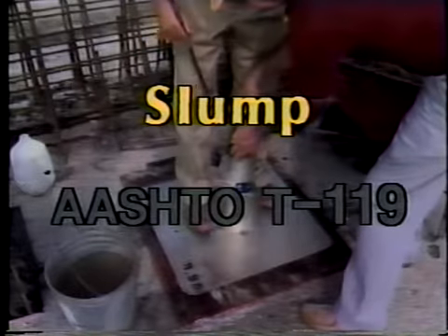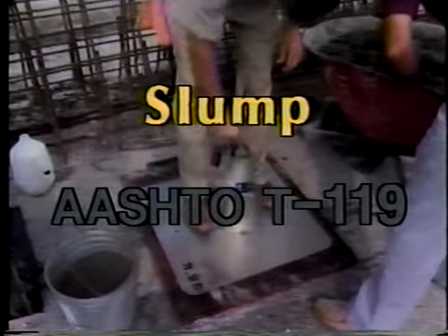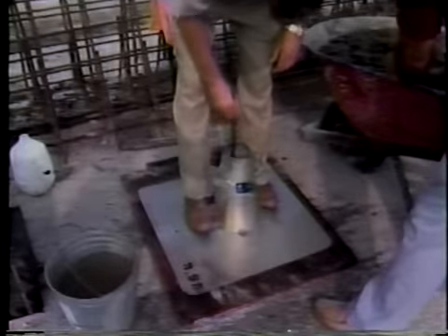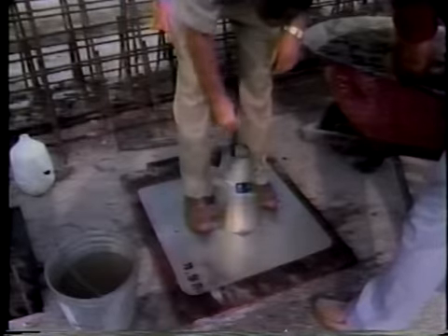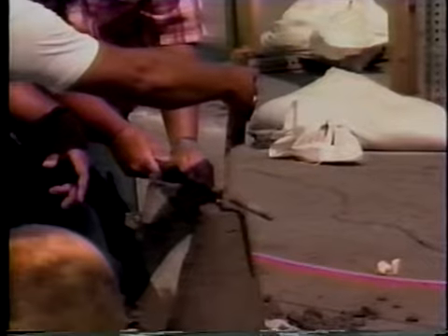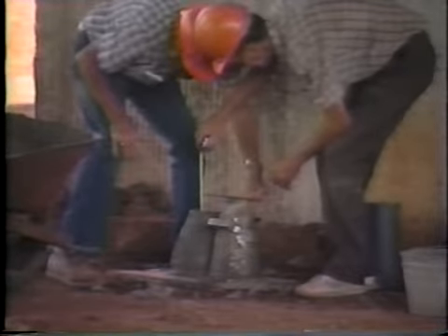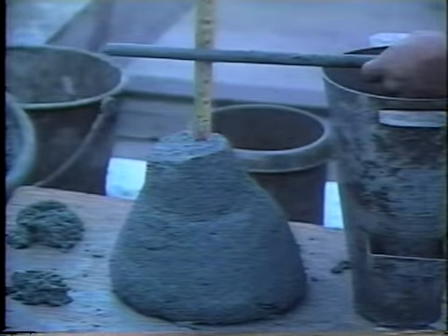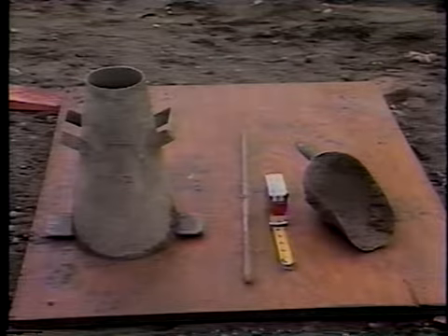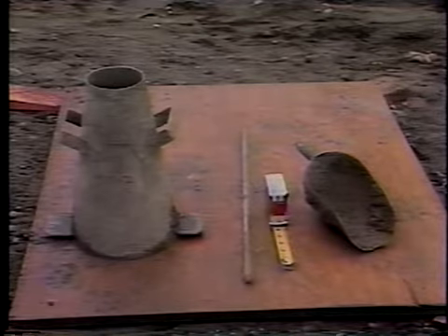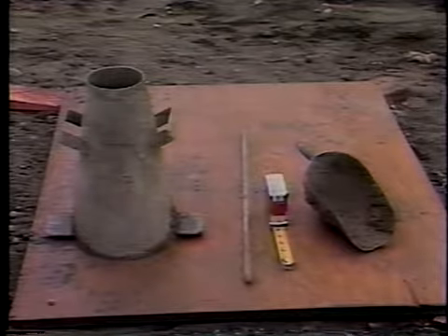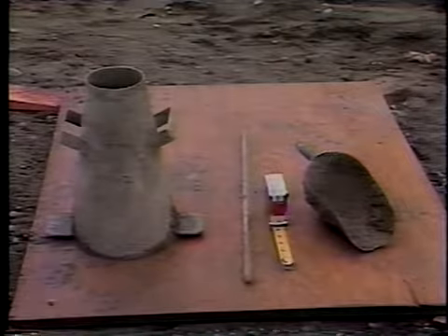This is by far the oldest and most widely used test to measure the uniformity and consistency of concrete. Variations in slump generally indicate that changes have occurred in the properties or proportions of cement, aggregates, water, or admixtures. The equipment needed for slump tests includes a standard slump cone, a standard tamping rod, a scoop, a base, and a ruler or measuring tape.